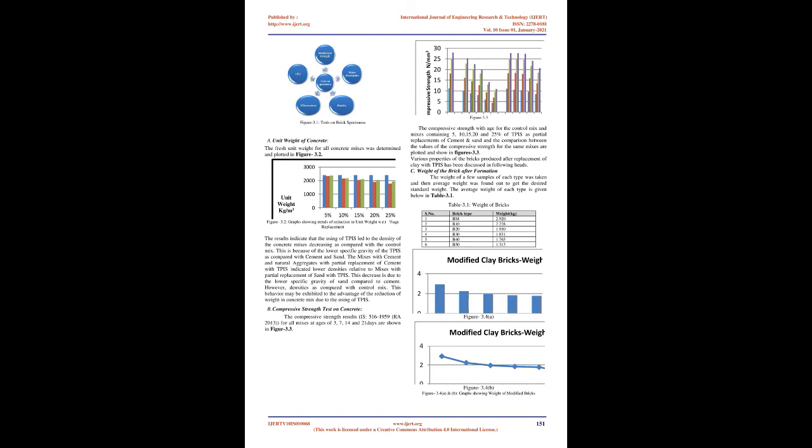The specimens were demolded and sun-dried for 3 to 4 days. Samples were stacked as shown in figure 2.6 and then were fire-burnt in the kiln. More than 250 successful brick specimens were prepared for carrying out various tests. Bricks are burnt at high temperature.